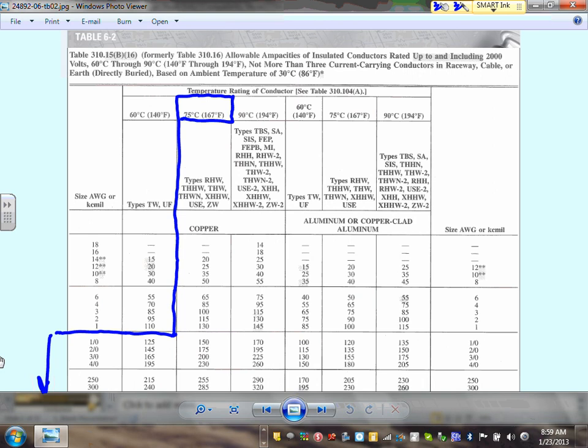That's the default. In three-phase equipment, if you have three-phase equipment, your default is always 75. So when you size equipment, you are in this column right here. So 4 can get me 230 amps. Done, 230 amps.